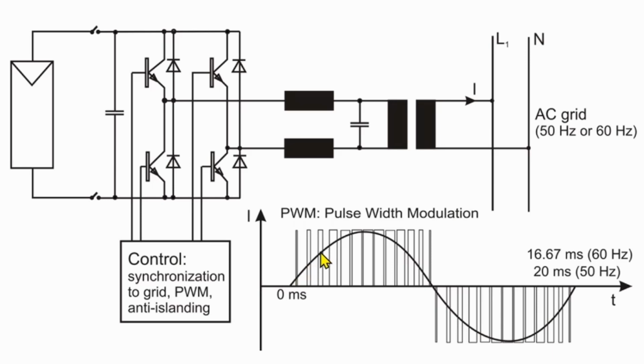The current is rising. The length of the pulse is increased here, and here at the maximum current, you have almost a full duration of your pulse width. And then the pulse width is reduced, and then you do reverse pulses. So you switch off that switch here and ignite that switch. So this part of the circuit is then negative biased, and this gets then to the positive part. You ignite that one and switch off that one. And then you can create negative pulses here and do the same as you did before. Then you have this pulse pattern here.